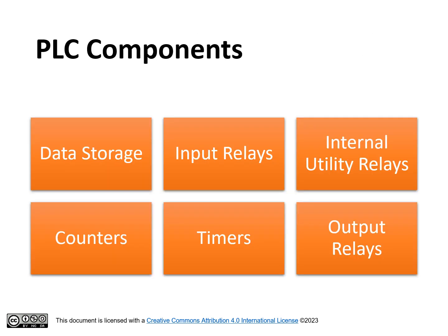To better understand the program control instructions, it is essential to be aware of the main PLC components. Data storage. Compared to traditional computers, data storage is limited. These storage spaces can be volatile, registers, or non-volatile memory space. The registers are typically used for operations requiring fast access, such as those for data calculations and manipulations.